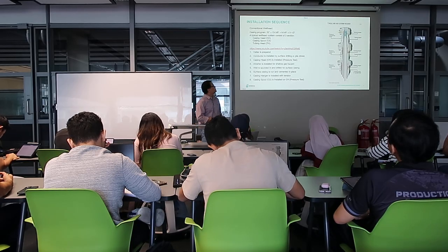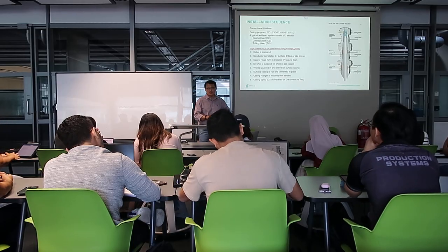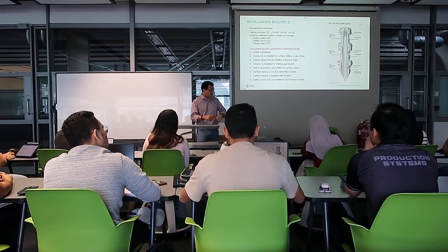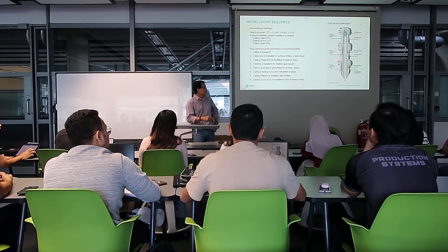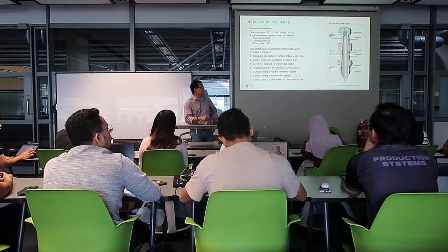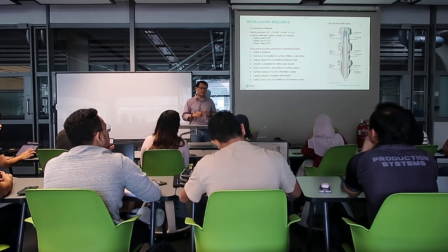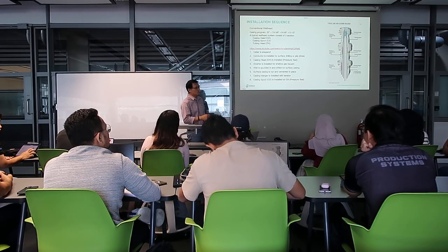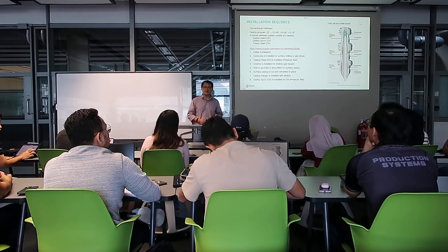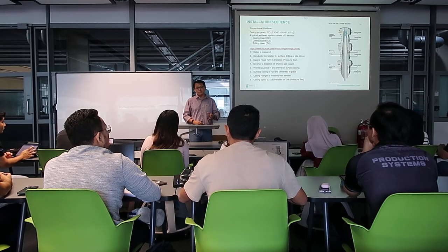Okay. So this is the whole installation sequence. This is really a typical conventional wellhead, where we really have a casing head as a starting. Then we have the casing spool, then we have the tubing head. So when we construct this well from scratch, the first thing is we actually have the cellar prepared. Imagine this is an onshore well. Let's start with the easiest one, which is the onshore well. Offshore typically is more costly.